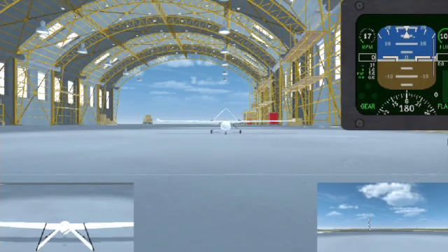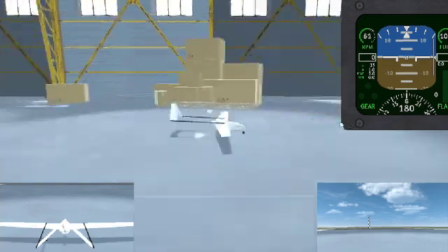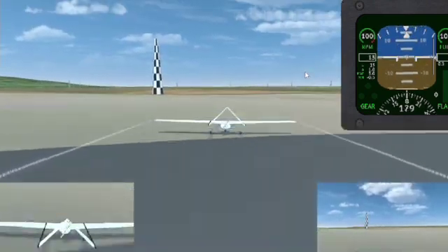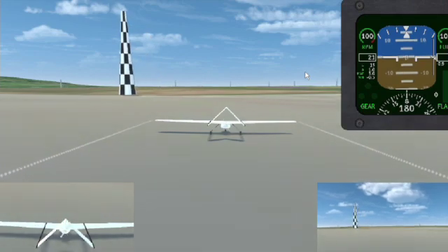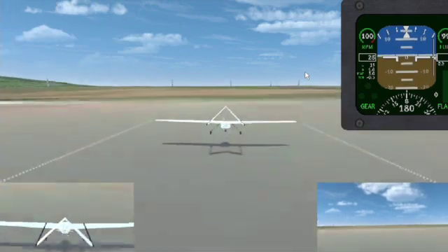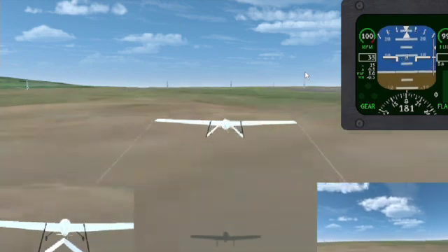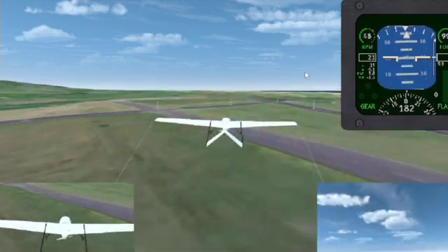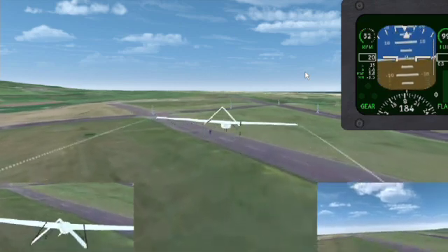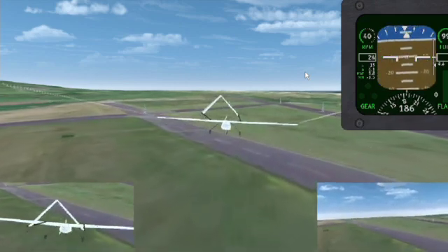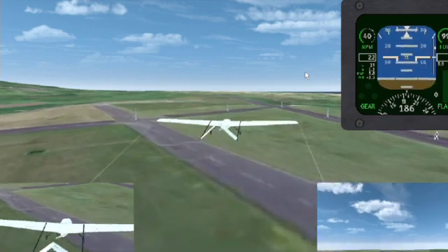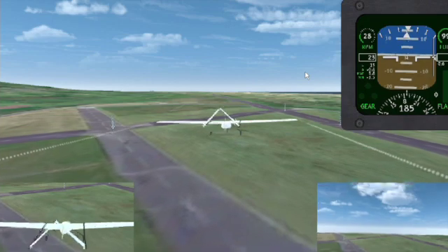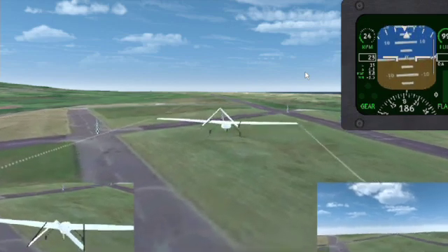Alternatively, when the center of gravity is at 0.05, the UAV is more stable and is much easier to fly and maneuver. Also, when there are no control inputs, the takeoff speed of the UAV is around 50 meters per second, and at an altitude of 100 meters, trimmed flight is achieved at 21 meters per second for an RPM of 28,000. The lowest speed at which the steady flight can be achieved for this UAV is around 16 meters per second.